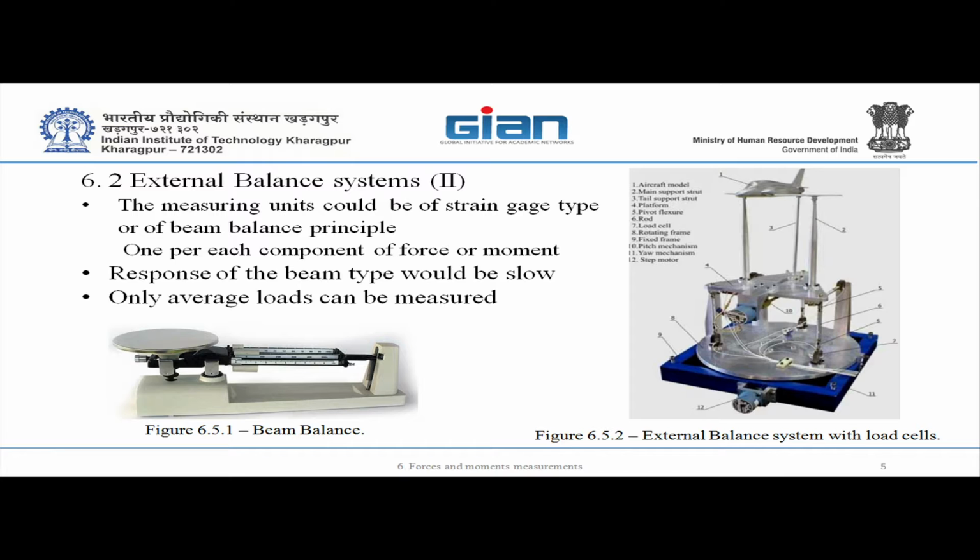So you have one of these, right? External balance. I'm saying that for the external balance capability, instead of replacing the beam balance with strain gauge, what people do is fit some kit in order to be able to connect the model to a sting balance. That's what I'm saying. So you use the struts only to hold the system, this kit, and you use the struts only.